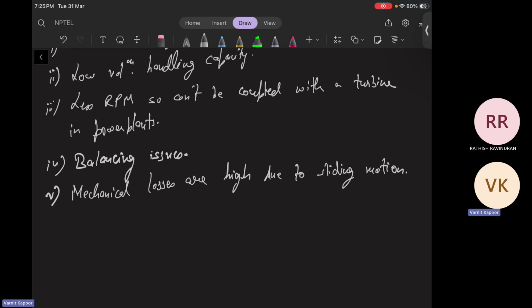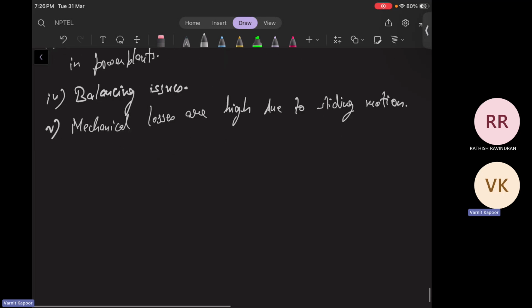Now let us see the compressor where we are giving the work input to the compressor without the clearance volume. There is no clearance volume. As we used to have in an IC engine, we used to have a clearance volume so that valves don't hit. But suppose if the clearance volume is not there, then how will the work input be calculated? So let us come to case one. Work input to compressor without clearance volume.